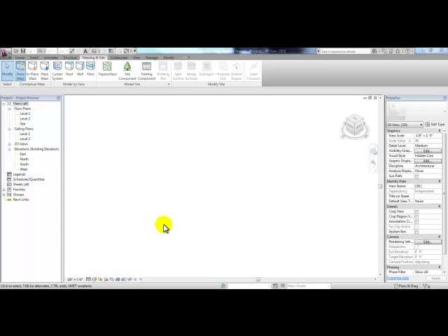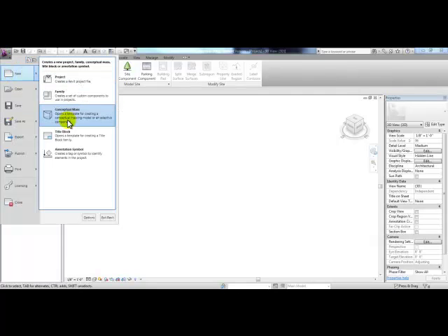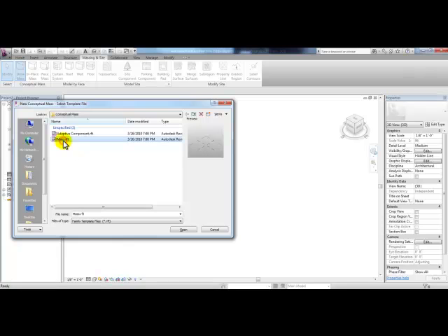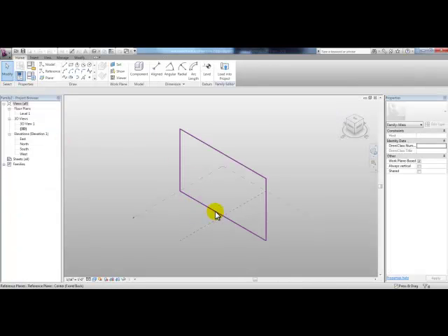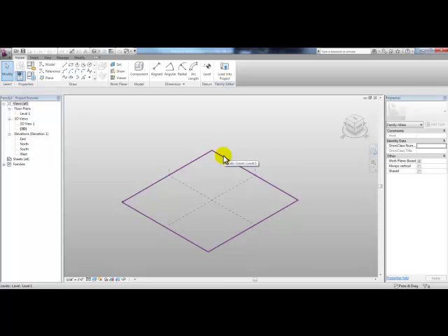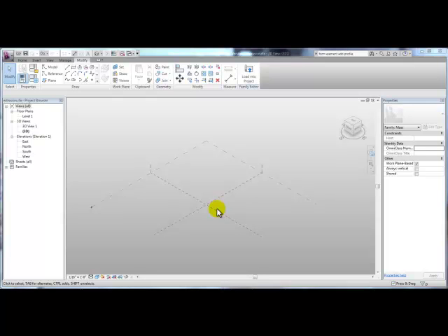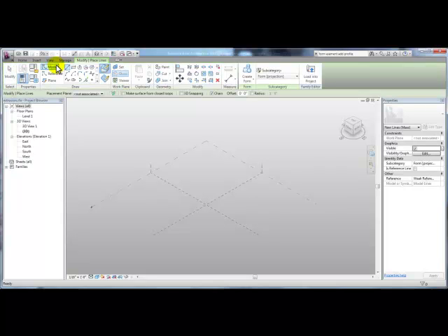Starting a new Revit file in the 3D view, under the Massing and Site tab, you can create an in-place mass working within the Revit environment, or you can create a new conceptual mass using the mass family template. By using the family editor or template, you'll be able to see the reference planes and the levels and customize your mass with parameters that are formula driven, and save the family file so that you can use it in different Revit projects. We'll start by using model lines.